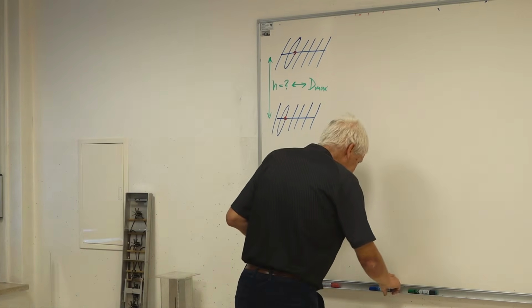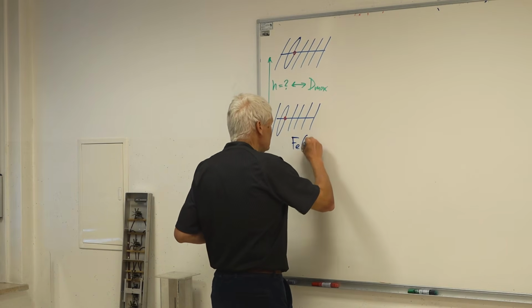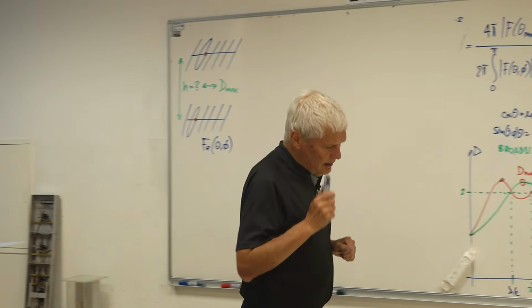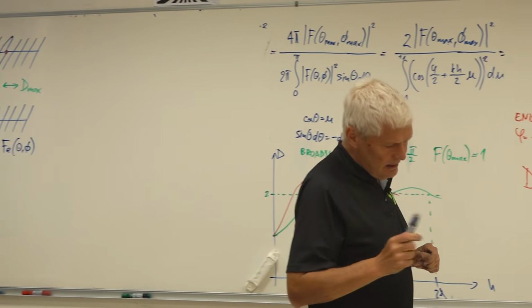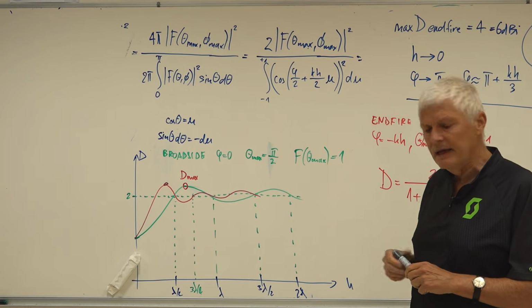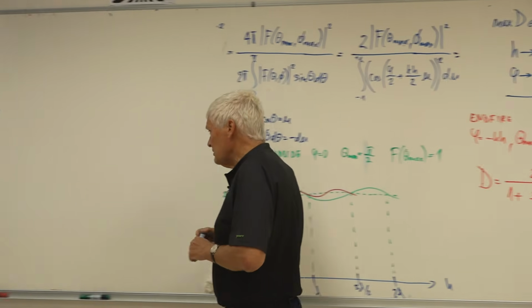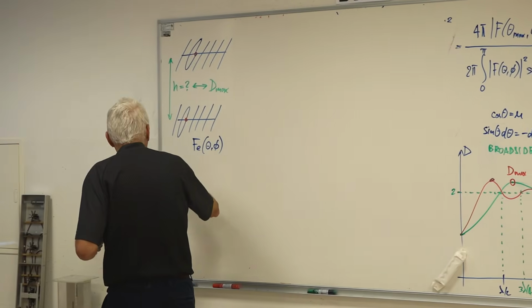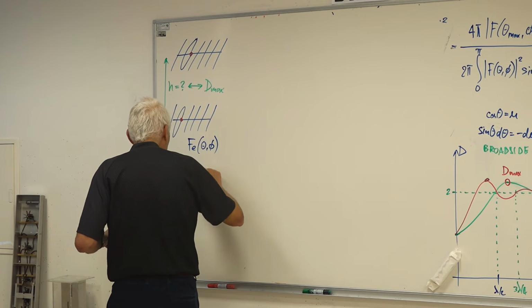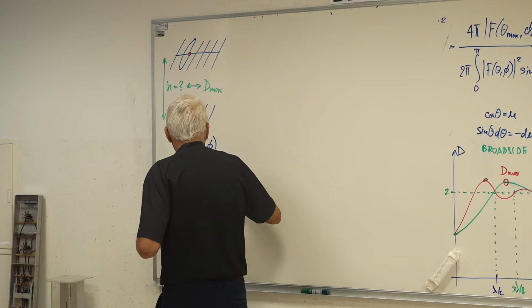One idea is I can measure the element radiation pattern of each antenna. But this radiation pattern is in two dimensions, in theta and in phi, and it is a complex measurement. It's expensive, and doing it correctly is very difficult. The direction pattern of the array, f of theta and phi, I can calculate.